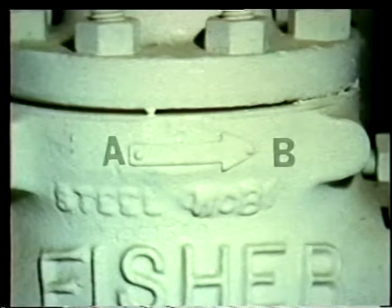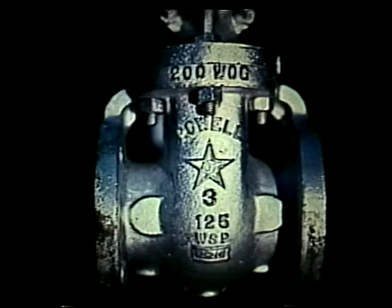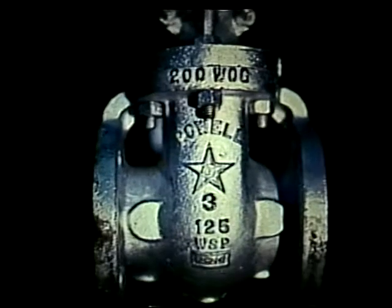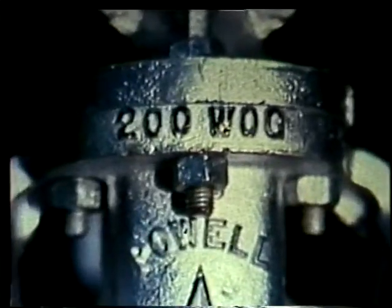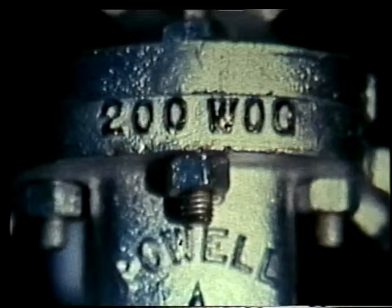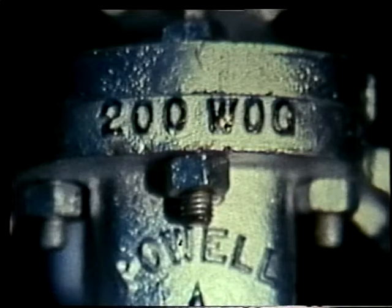An arrow or set of letters also may be used to show the direction of flow through the valve. You'll find service markings on the valve too. These will indicate the operating range of the valve. For example, on this valve, the number 200 is the maximum allowable pressure that can safely be placed on the valve. These letters, WOG, stand for cold water, W, oil, O, and gas, G. They are for pressure ratings other than steam.